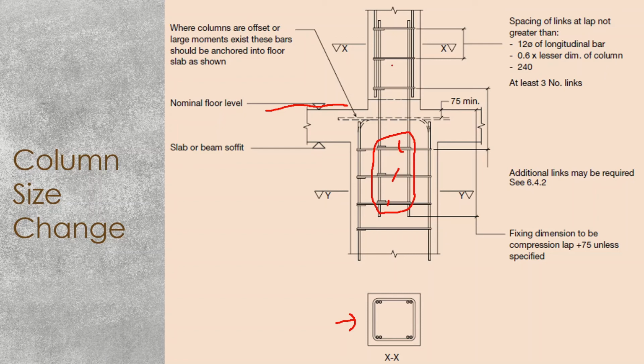This is because now this load will be applied to the center of the column. Tensile stresses will develop and there will be confinement issues. Therefore you have to provide a column strap there. In addition, you have to follow the spacing requirement for shear links.